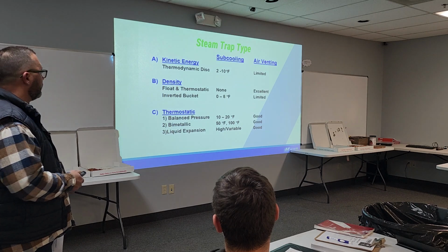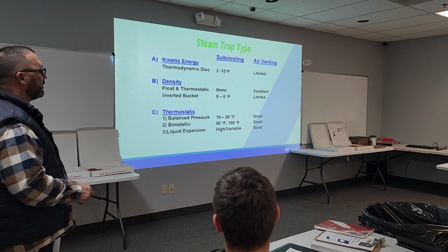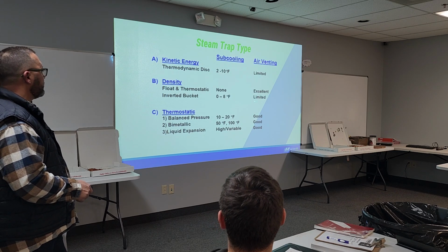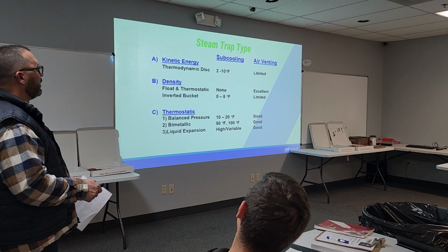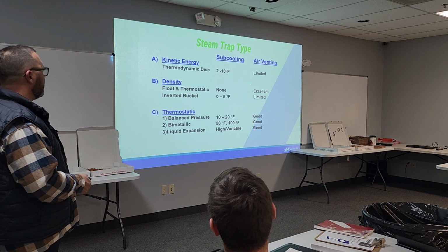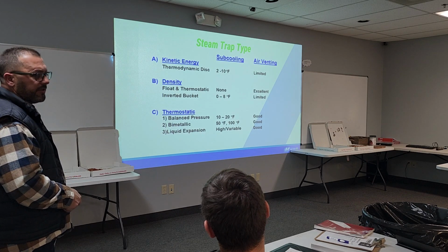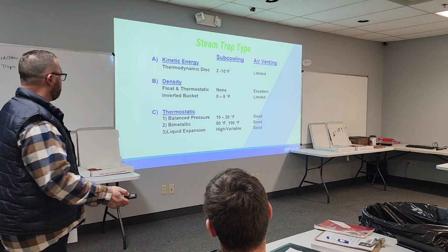And we're going to get into a little bit more of that. They have very limited air venting. And again, if you've got a steady pressure application, they do well. If it's modulating and there's air, and if it's a system that gets shut down on the weekends and started up every Monday, it's going to take forever to get those heated up, and you're going to have to open valves and do what we call a supervised startup.